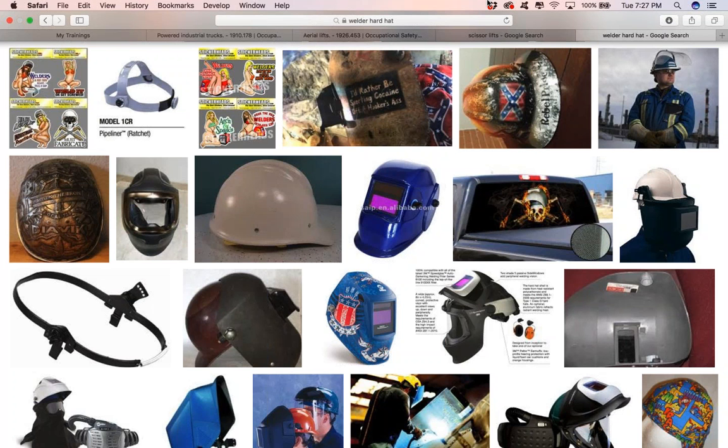What's the easiest way to know that we have the right rated gloves for welding purposes? Check the manufacturer specs on those gloves. If they say that they're acceptable for welding, and acceptable either for gas and/or for electric welding, then we know we can use them. Okay, so fall back on the manufacturer, fall back on your supplier, folks, so that you make sure an employee is appropriately protected.